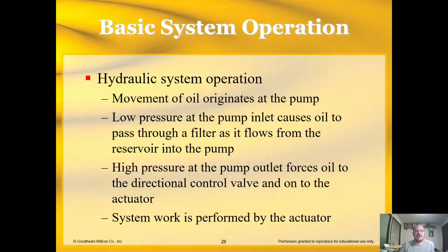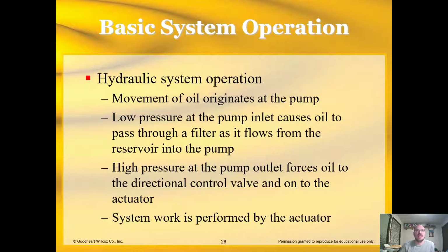So how does hydraulic system operation differ? Okay, so they're talking about operation here. So in hydraulic system operation, the movement of oil originates at the pump. So we have oil coming from our reservoir to our pump. We'll talk about how the pump works, but a pump essentially draws the fluid in, and then it pressurizes it, pumps it out, right?